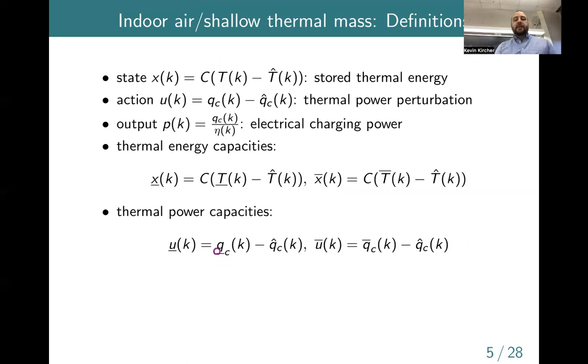And then similarly, the equipment is going to have capacity limits, which in general can be a function of time. So we basically define the upper and lower limits on the perturbation, the adjustment, in terms of the baseline Q hat, and then the Q max and Q min for the equipment.